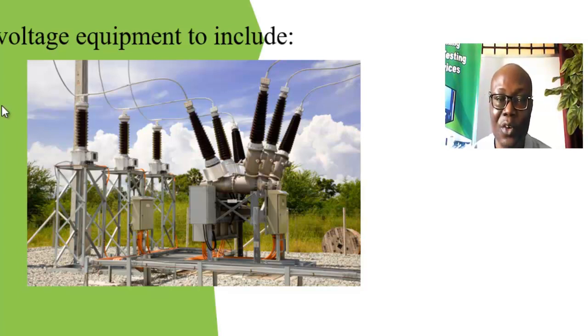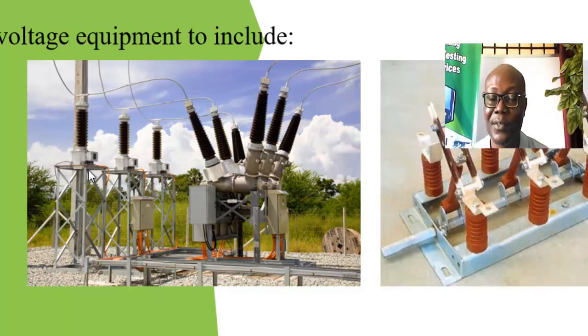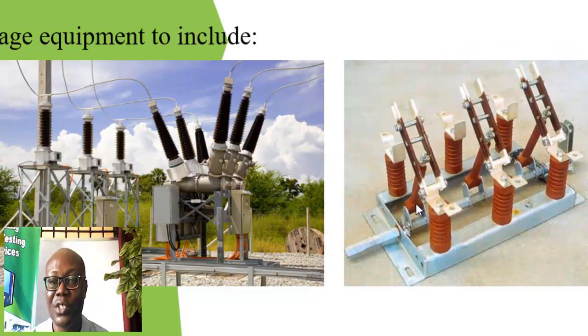You can even use it on lightning arrestors, to get the insulation of the line to ground, whether it is still fit. Then disconnector switches, like the circuit breaker: between poles, between pole to ground. Basically, those are what you can actually test on the isolator.